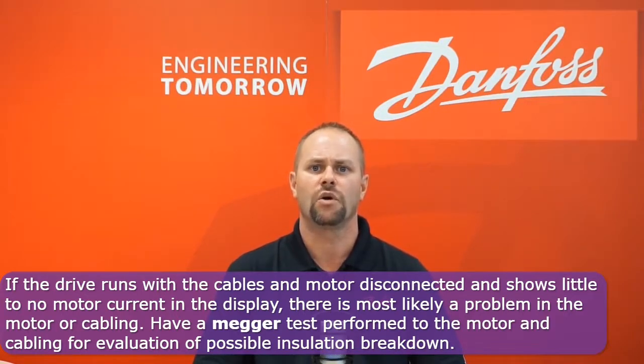It's important to note that it's a common misconception that if a motor runs without issue directly across the line, such as in bypass mode, that the motor is good. This is not necessarily true. A drive sends out high voltage, high frequency pulses which will find paths to ground through the smallest of pinholes in the insulation, where an AC sine wave will not.